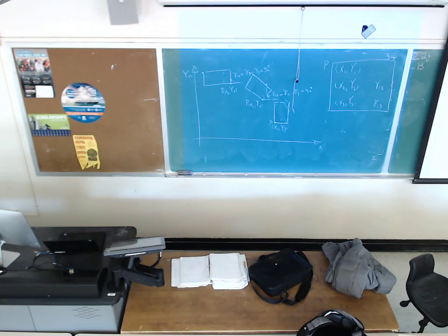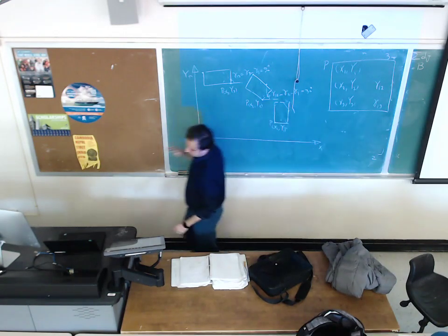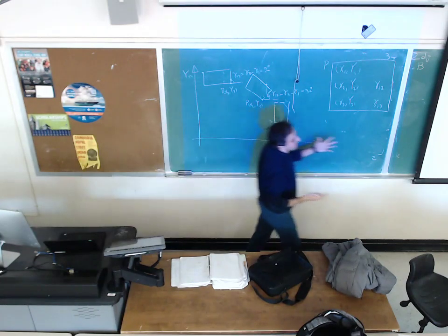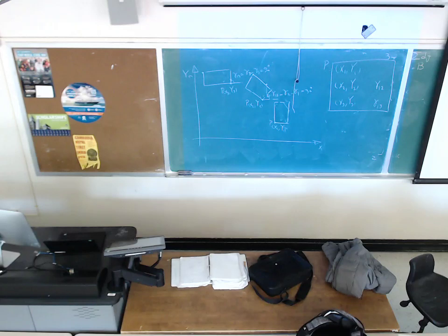1 is ground, 2 is a coupler, 4 is this guy, such that one point of that, which is point B, moves along these 3 precision locations. Also, this wing is rotating by the angle of gamma 1,2 from first to second, and gamma 1,3 from first to the third. So the goal is finding the location of the joints O2 and O4 and sizing the length of all 4 links.